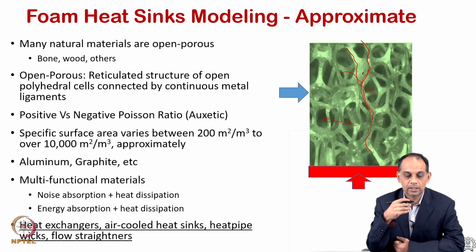With that increase in specific surface area also comes the situation that when there is flow, you may encounter new types of problems in terms of penalties in terms of increasing foam drag or skin friction and some separation effects causing more pressure drop to occur.